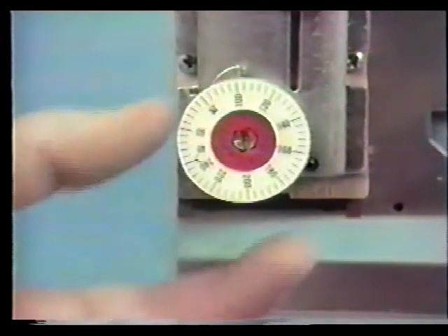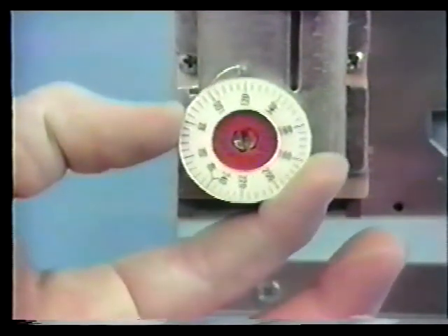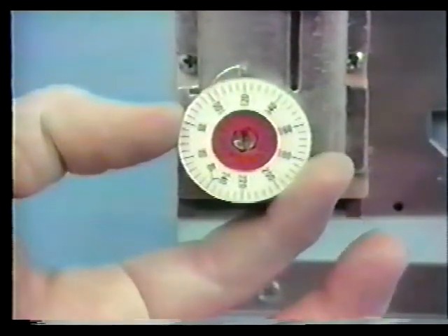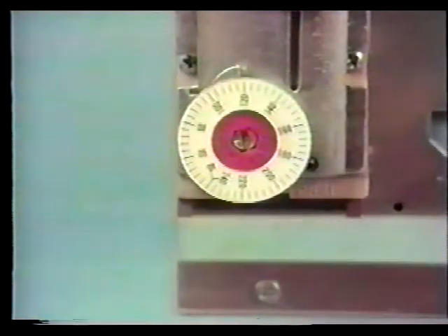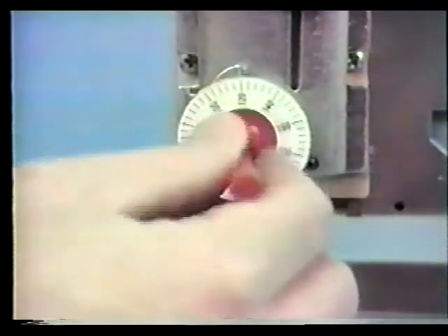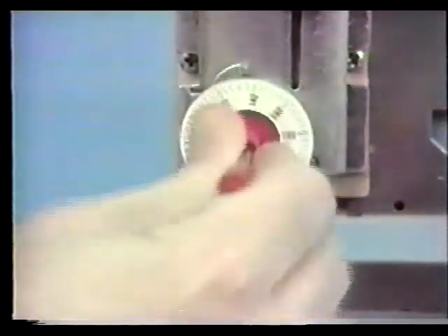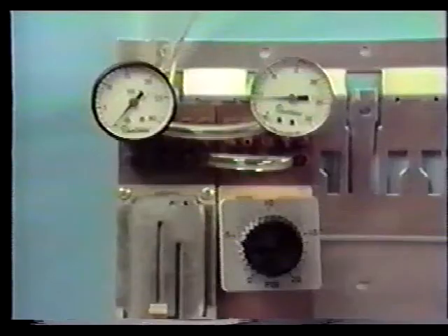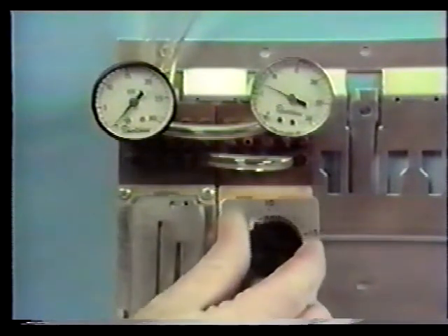Adjust the control point scale to match the calibration point by lifting the ring and turning it to match the input from the primary transmitter. Adjust the control point adjustment with a calibration tool until the control point scale indicates the desired set point. The calibration procedure when utilizing a control point adjustment input is similar with one exception. You must set the input on the CPA port first.